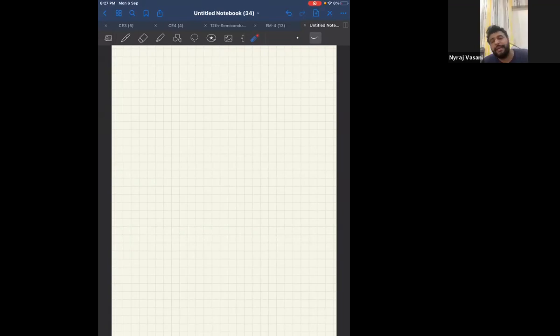Sign will be positive. That depends on KVL. When we do KVL, we have to see whether our direction is opposite to the direction of the current that they have given in the diagram. Then the sign will be positive if we go against their direction. Because in this question, they have given the direction of current. So if our direction is opposite to their direction in the circuit, you have to take positive. And if our direction is along their direction, then you have to take negative.